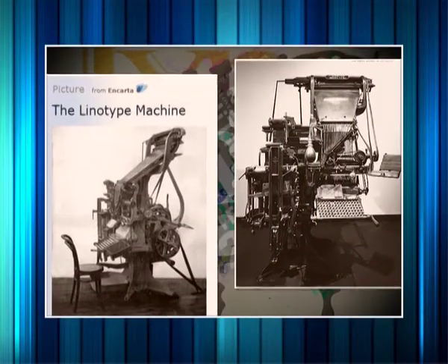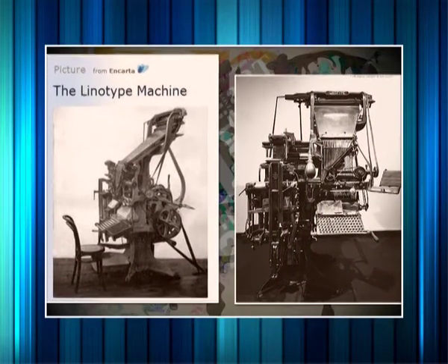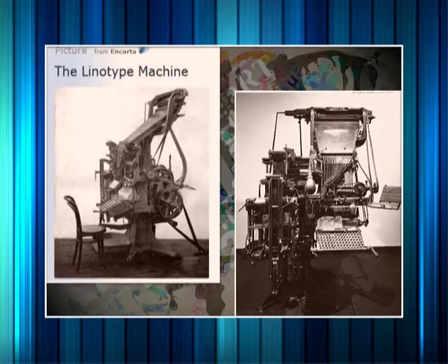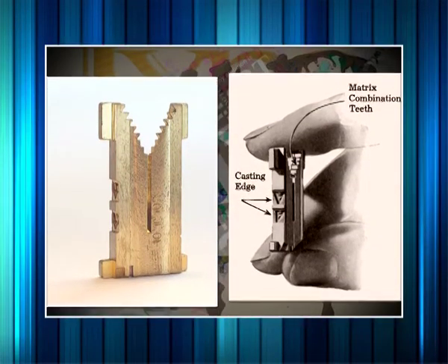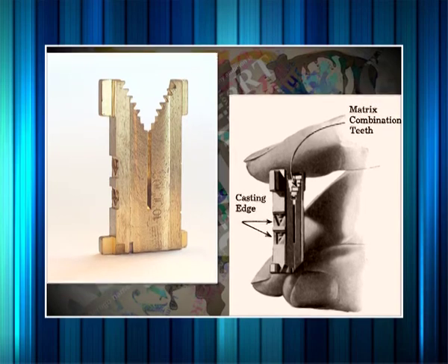These machines were used on the Morning Post until replaced by Linotypes in 1910. These words were separated by double wedge spaces used for justification. The line of matrices was brought in front of the mold, justified by means of the space bands, and cast into a slug. The matrices have teeth cut into a V-shaped groove on their upper part.